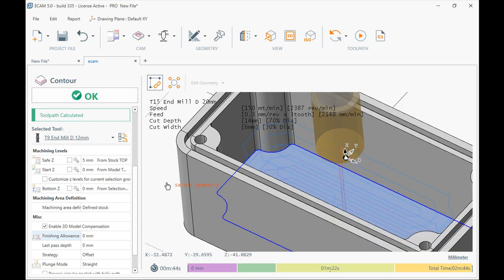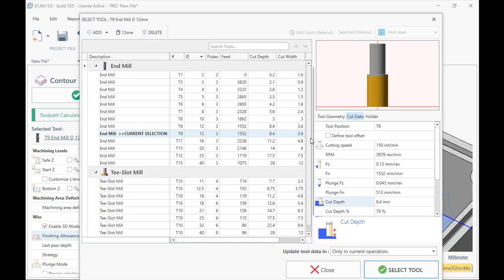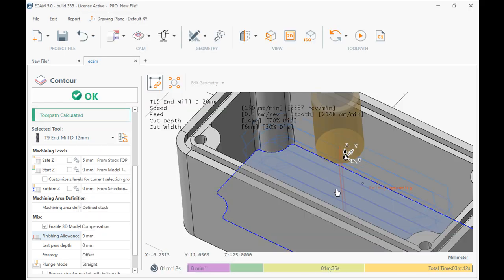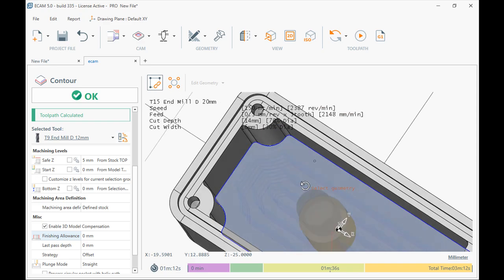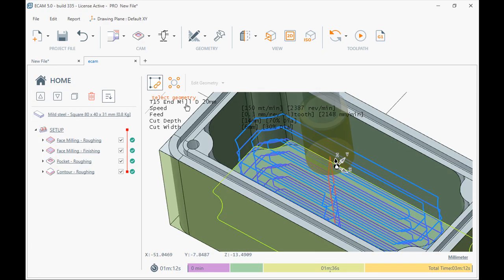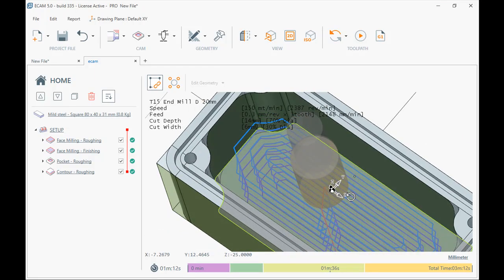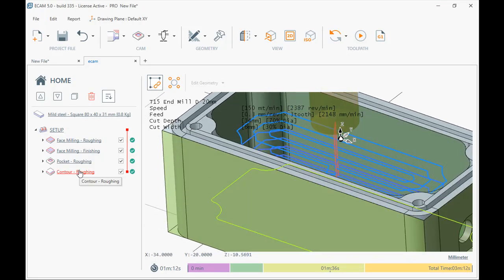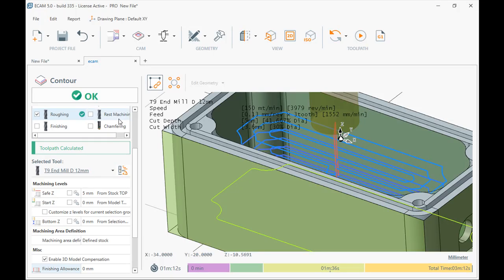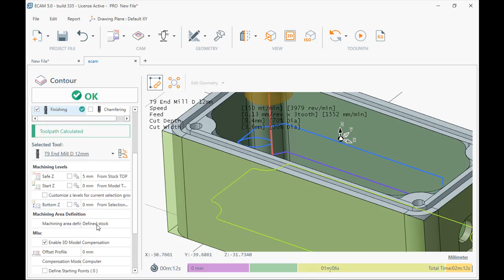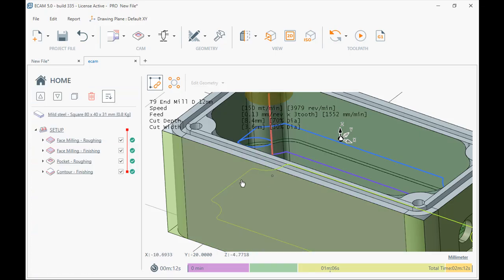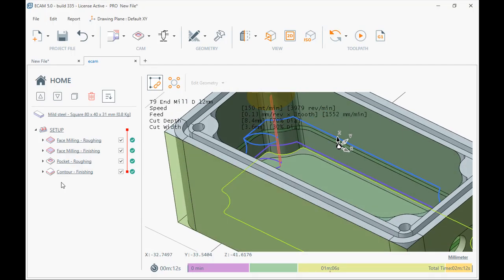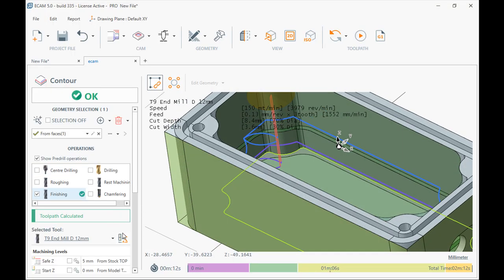Okay, 0, and I need to go there again because I want once more the 5 millimeter increment. So doing okay, and we have, okay, still a roughing, sorry, I don't want roughing here, I want the finishing, my mistake. 12 millimeter, 0, and now it should be okay. Oh, sorry, but again, one mistake. I want more increments.